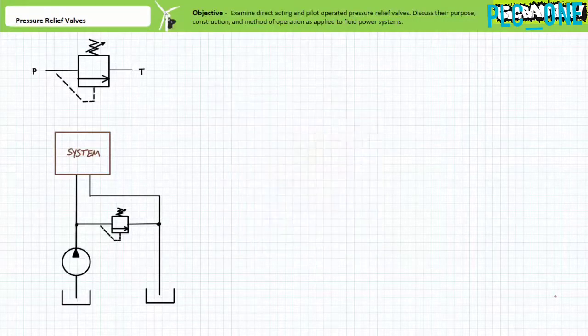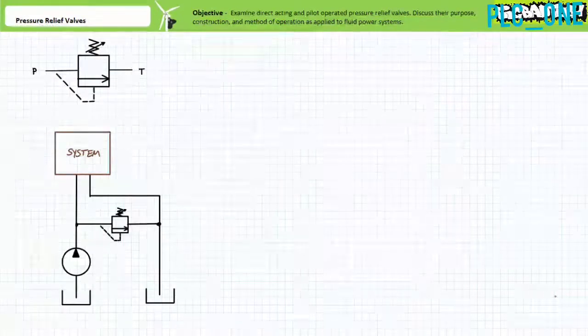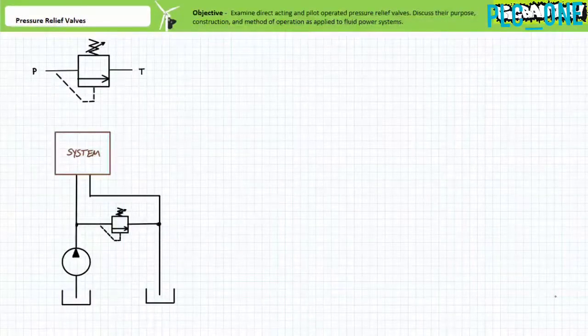It would be far better practice to store energy or simply stop supplying it if your only option is to waste it. This is to suggest that a well-designed system doesn't regularly block pump flow, minimizes the time actuators are stalled at the limits of travel, and makes the fundamental realization that when you don't need flow, you don't need to pump. We'll discuss these and other interactions in later lectures on directional control valves, accumulators, and pumps.